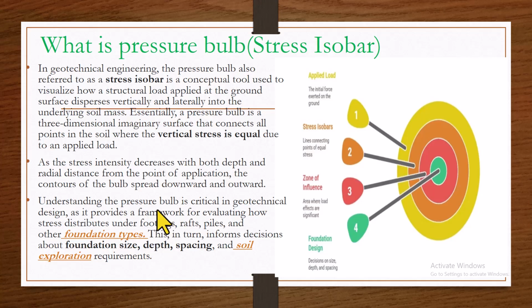So understanding the pressure bulb is critical in geotechnical design as it provides a framework for evaluating how stress distributes under footing, raft, pile, and other foundation types. This in turn informs decisions about foundation size, depth, spacing, and soil exploration requirements.